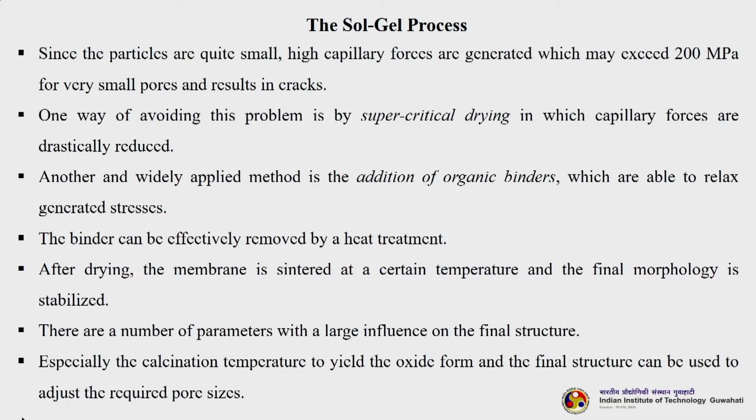Since the particles are quite small, high capillary forces are generated, which may exceed 200 megapascal for very small pores and result in cracks. So, this is what we do not want. Our intention is always to avoid the cracking during drying.